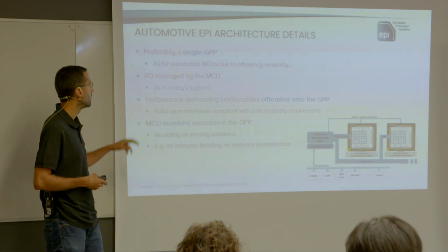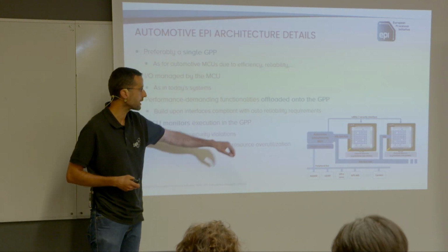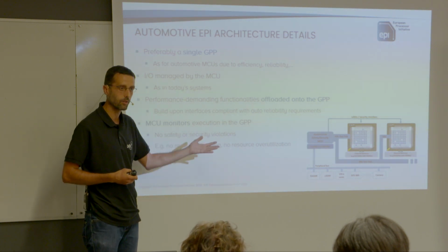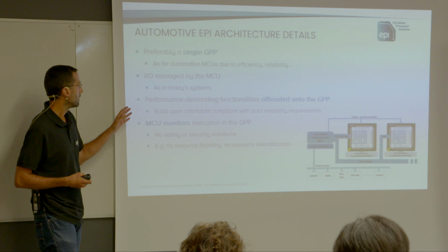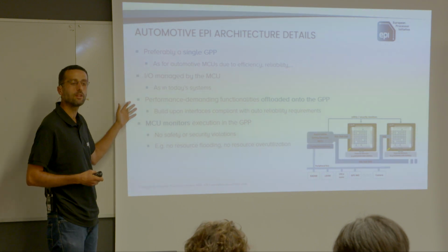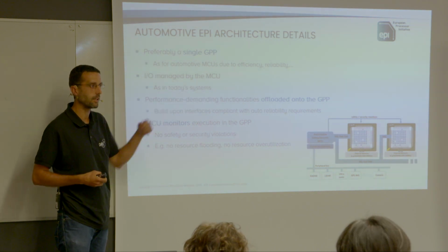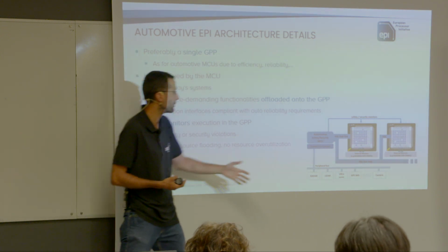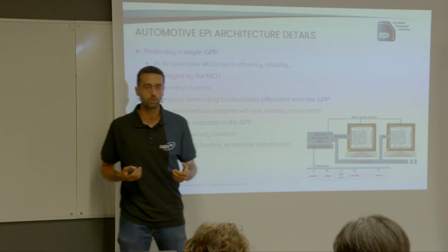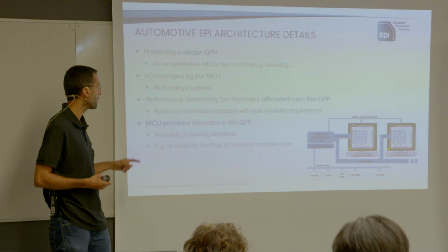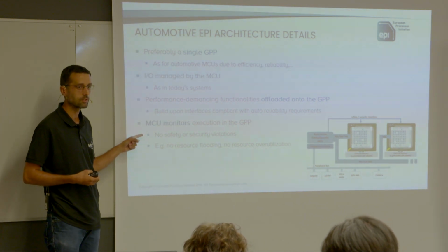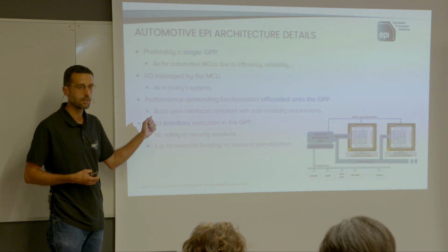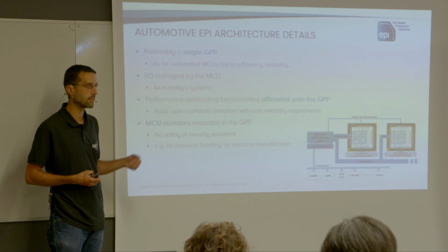It's just a matter of mastering this redundancy smartly so that we can deliver the safety we need for our systems. Input-output will be managed by the automotive microcontroller because it has enough power for that. Of course, it will be offloading in the high-performance chip anything that requires a performance level that we cannot deliver with the automotive microcontroller. And finally, it will be monitoring closely that any failure is detected in time and that corrective actions are taken in time.